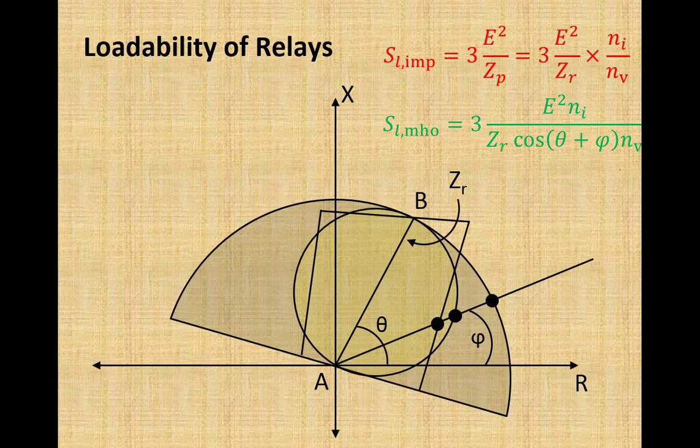And further higher loading capability can be achieved by a modified admittance relay characteristic known as shape 8. It looks like the number 8, the shape 8 relay characteristic, which has again the same reach, but the loading capability of this characteristic is much higher than the admittance and its counterpart impedance relay. We cannot compare it with the quadrilateral relay because quadrilateral relay characteristics are flexible.